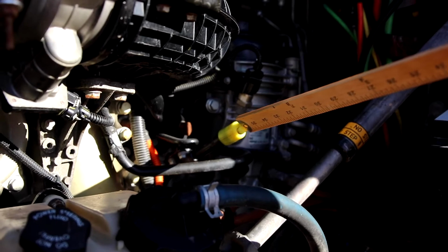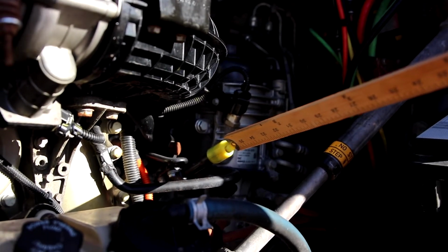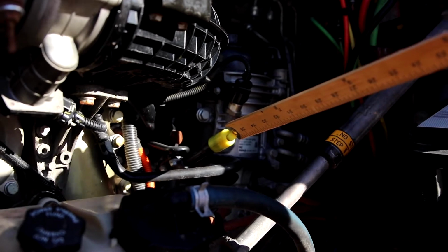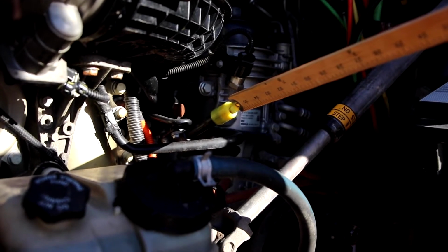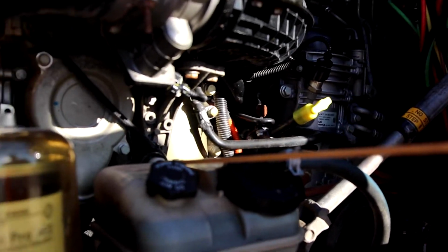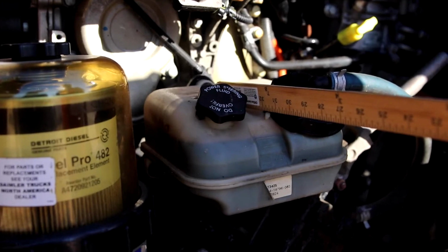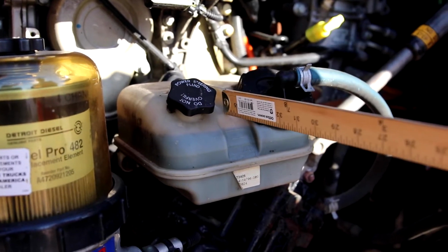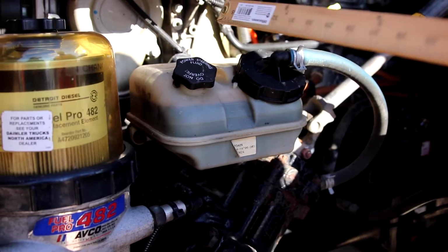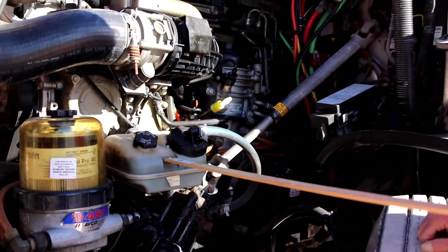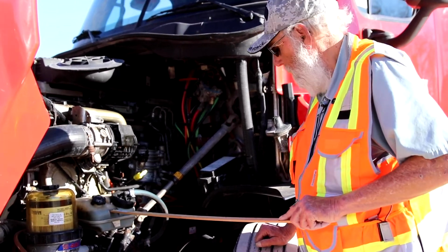And to check the oil, you would pull this all the way out, wipe it with a cloth, stick it back in, pull it back out, and check the level that's marked on the stick itself. Then you have your power steering reservoir. It is mounted securely to the vehicle, and again, it has a fluid, so there are no visible leaks. Check the proper level of the power steering reservoir.